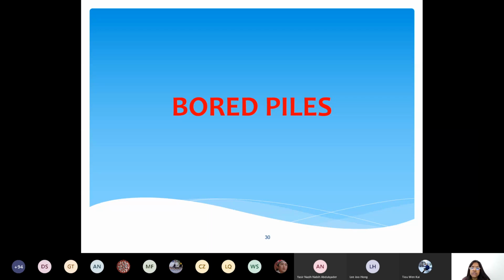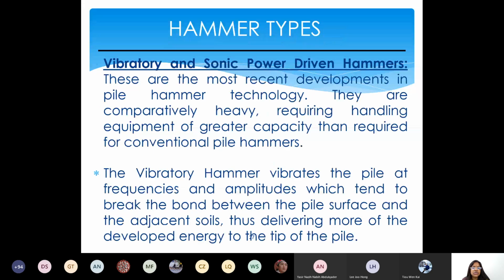That's why the approval is necessary. If you get proper approval, geotechnical engineers, professional engineers, will check based on the type of soil, whether the type of soil suits the type of structure and the type of pile chosen. It's a complex mechanism. That's why you see the preparatory things I just showed you.